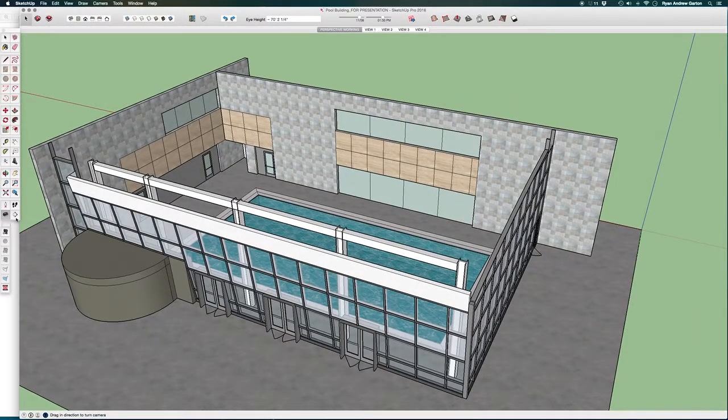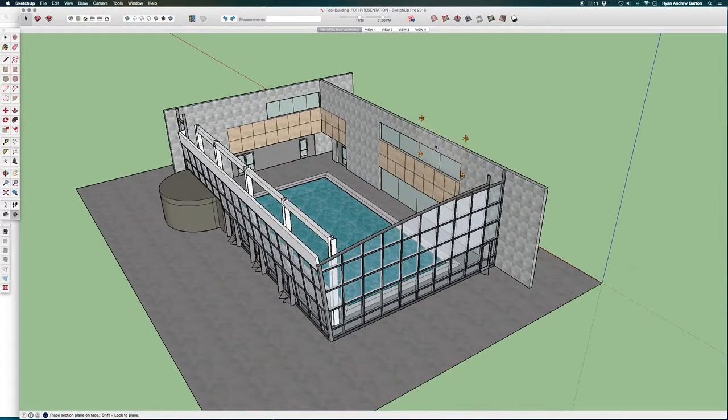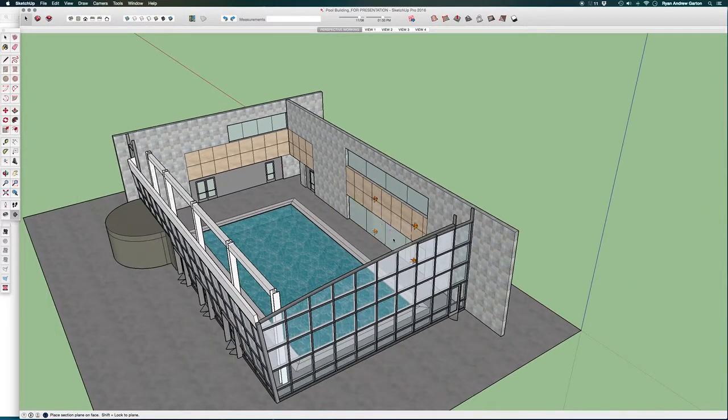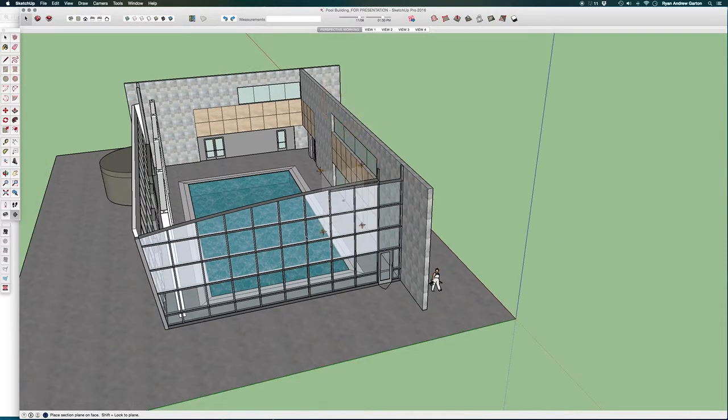Okay, in order to put a section in place, you have to click on the section plane tool, which is located at the bottom of the large tool set. It looks just like the section plane or section marker does on a drawing. Once I click on this section plane tool, it gives me an active section plane as my cursor. I haven't clicked again, I've just clicked once, and you'll notice that as I move, it's rapidly trying to find any face to reference, and the arrows point in the direction of the plane and which direction it's going to make the cut.